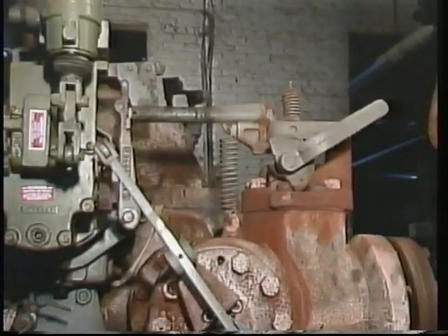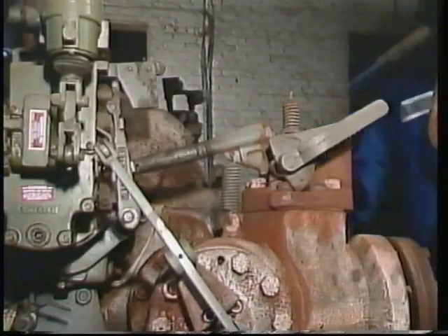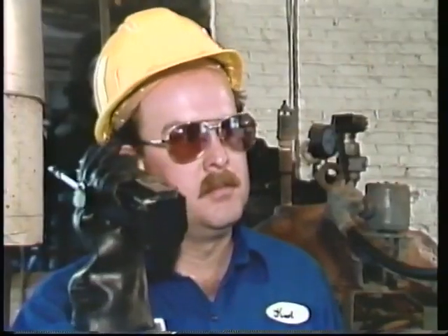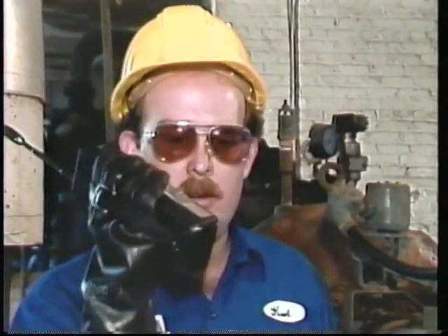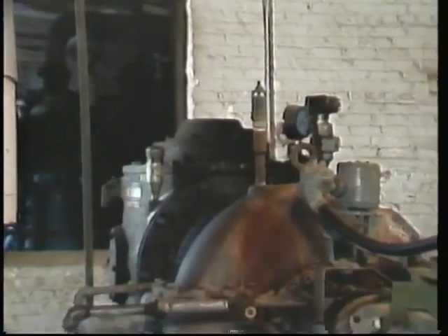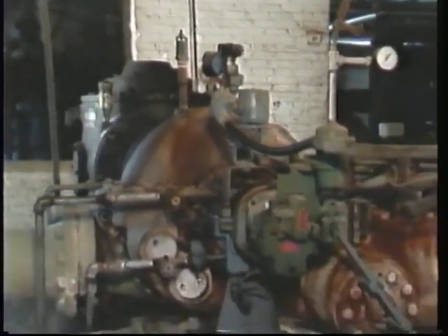Normal shutdowns, like the examples we just saw, are the kind of shutdown procedures you'll be using most often. Situations can occur, however, where there's no time for a gradual normal shutdown. Instead, an emergency shutdown must be performed to safely stop the turbine as quickly as possible. To accomplish this, simply trigger the overspeed trip by hand. Then, as soon as the situation permits, you can complete taking the turbine, its auxiliaries, and the driven equipment out of service just the same way as it's done for a normal shutdown.